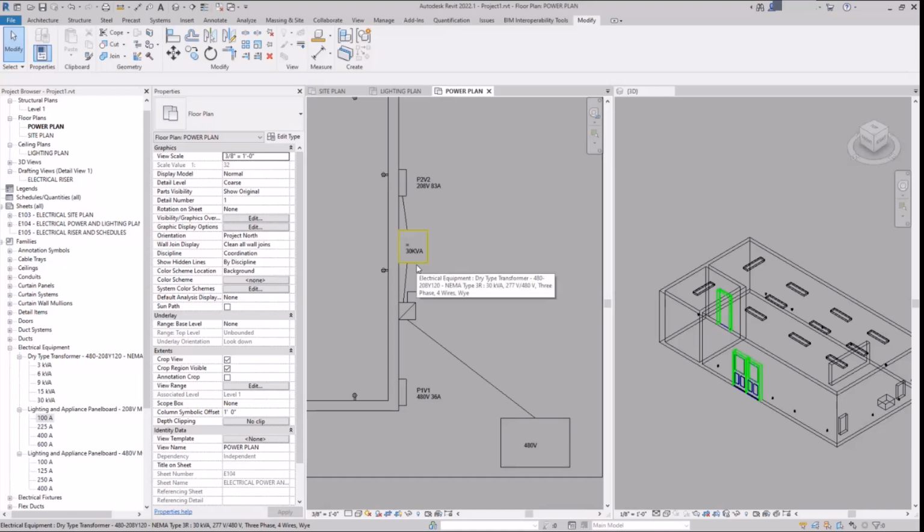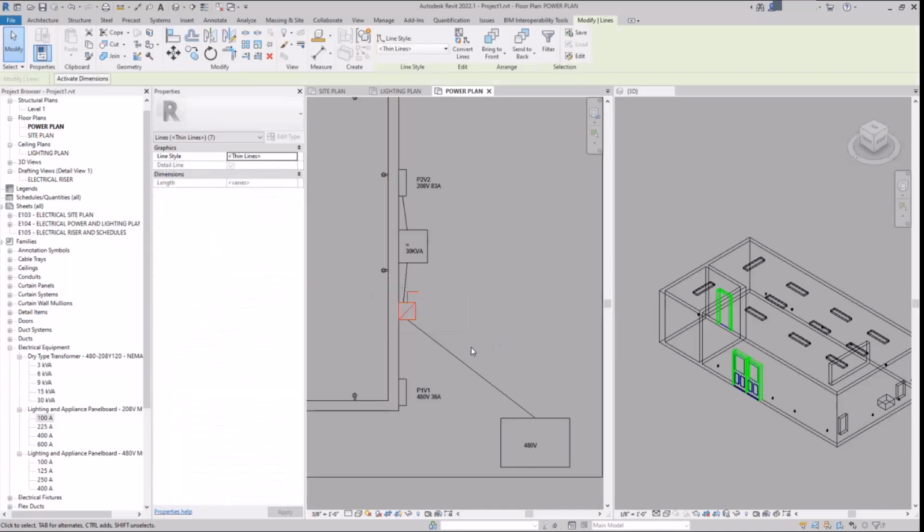And what is the disconnect exactly doing? A couple of things. So this would be an SE rated, service entrance rated disconnect, meaning it's a lot more heavy duty than a generic general duty disconnect. It's got specific things about it that qualify it as service entrance in case things blow up. It needs to be able to sustain a little bit more.